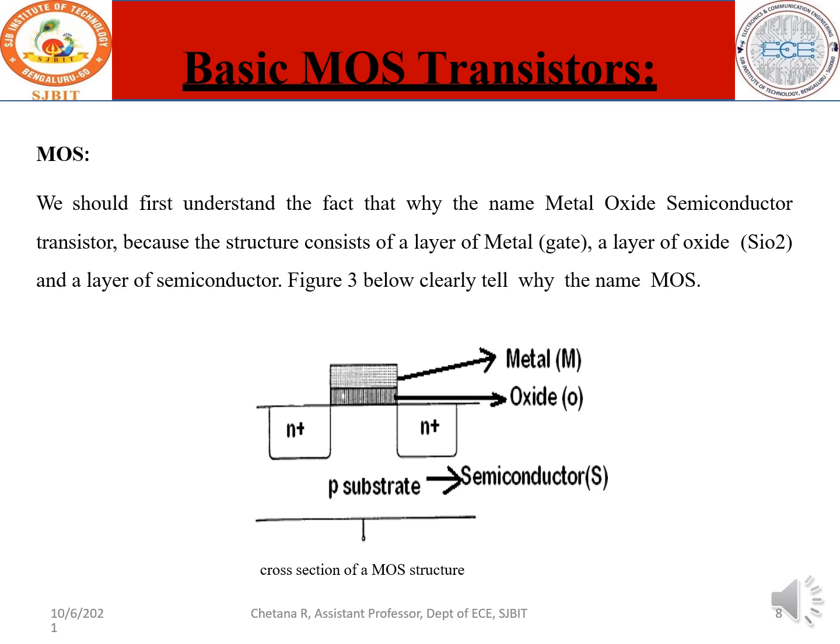So you have the metal, you have the semiconductor, and you have the oxide. Above the oxide you apply a layer of metal, and the appropriate metal applied here is called polysilicon, which is another version of silicon itself, which exhibits metallic properties, and that in fact behaves here as a gate. So metal is normally the polysilicon, and that is the reason we have MOS, MOSFET. So MOSFET is a layered structure with metal behaving as the polysilicon, oxide is nothing but the silicon oxide or silicon dioxide, and then you have the silicon as a substrate.